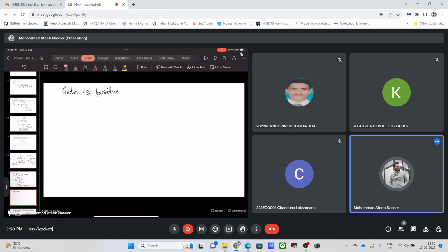So if now we consider this gate voltage, if the gate is positively biased, it would mean that Vg is greater than 0 and there will be Fermi level shifting. The Fermi level in the metal side will be lower than the Fermi level in the semiconductor. This would result in a slope in the energy bands in both the insulator and the semiconductor.